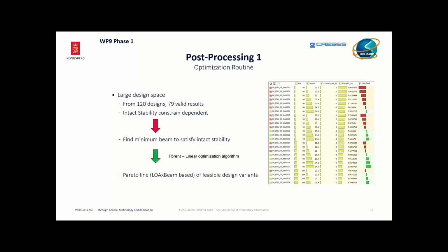In order to organize some of the design optimization routine, we then permuted the design space, increasing length and beam slowly. Draft was automatically calculated to give our required deadweight. So shorter and narrower designs have higher draft in order to give 4,500 deadweight capacity.